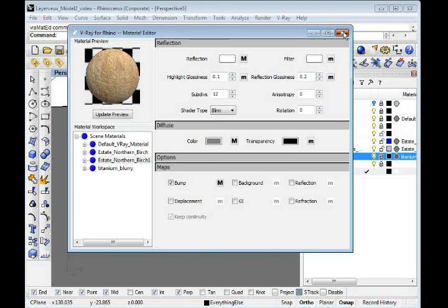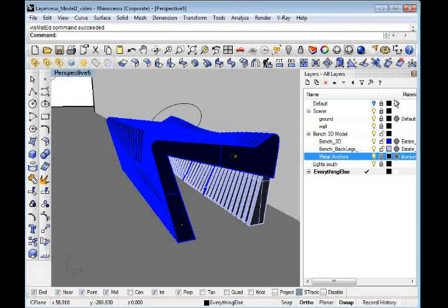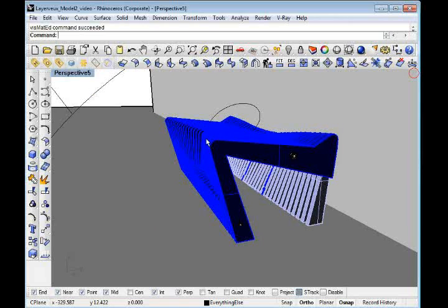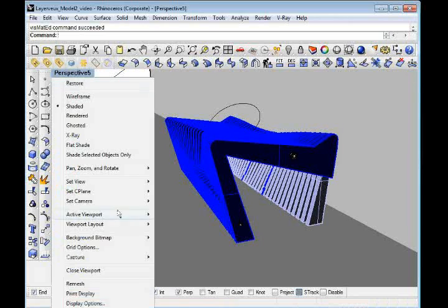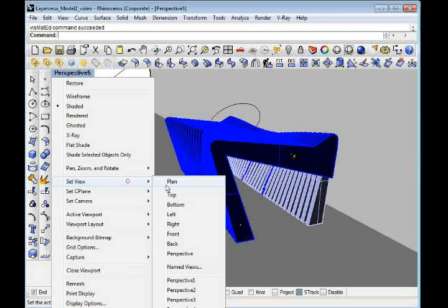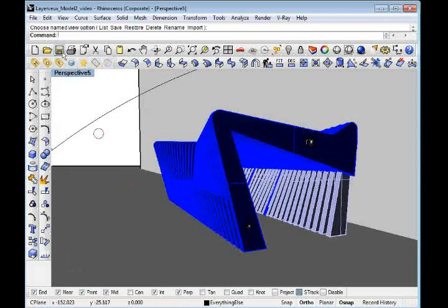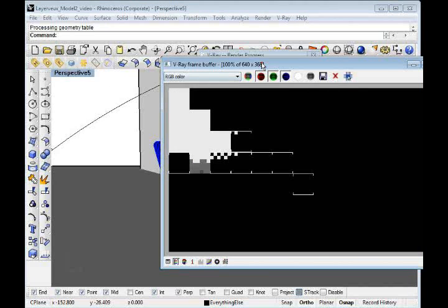So close that out. Okay, and then I believe I'm good to go on the layer, so I'm going to close out my layer property box. Go back to my perspective and change my viewport to my desired view. Hit save. Make sure you save everything and save it often. And then hit this little shaded box, which is render, and render it.